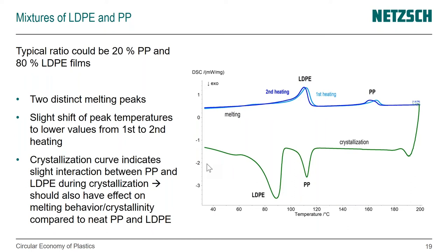But a lot of amorphous materials and semicrystalline materials, you can distinguish also with FTIR. So if you're not happy with the DSC result, you should be able to see it as a step, and you should see the other materials as peaks. You might need to use other tools, but it's also not possible to quantify amorphous plastics with the DSC method.